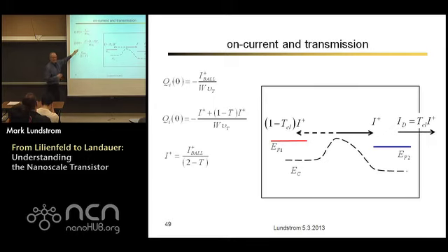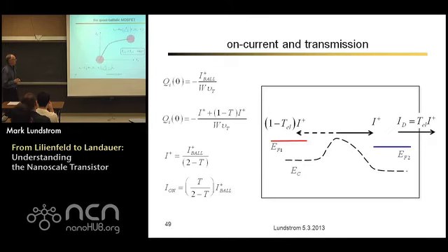And what I'm going to find is that when I have scattering, I'll inject fewer electrons because I'm going to get some charge contributed from the ones with negative electrons. So when I maintain that the charge always has to be given by MOS electrostatics, whether there's scattering or not, that's where this 2 minus T comes in. And then what goes out is T times what came in. So now I've got my T over 2 minus T. The point just is that you have to understand MOS electrostatics in order to get this expression right. And that becomes important at high drain voltages.